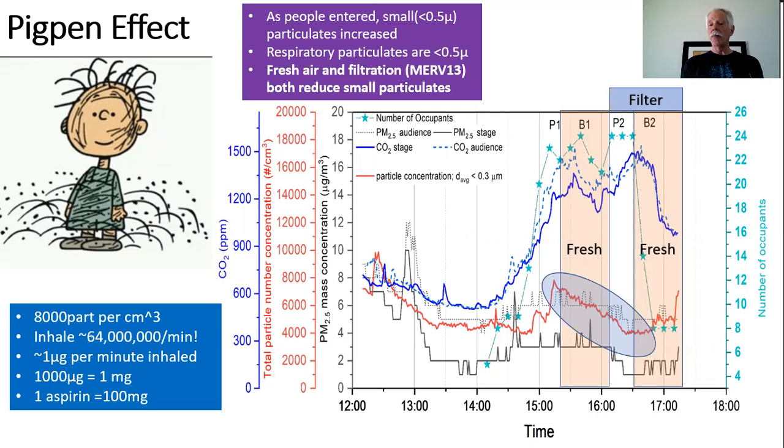And associated with that carbon dioxide will be respiratory droplets just from your regular breathing that you're going to exhale, very, very small droplets in this submicron range. And a human hair has a diameter of about 100 microns. So 0.3 microns is less than 1% of the diameter of a human hair. And then for those time periods when somebody is coughing or sneezing and shearing off bigger droplets from the liquid film that's in your throat, these droplets were more in the, say, 5 to 10 micron range.